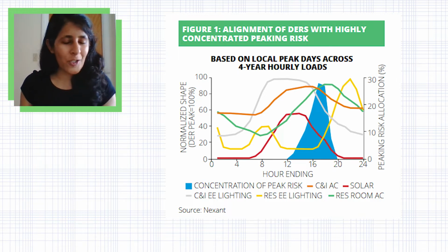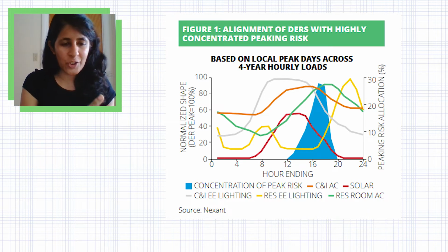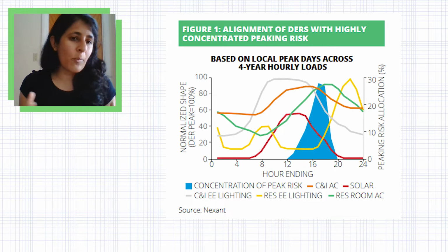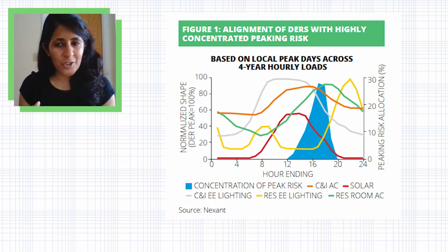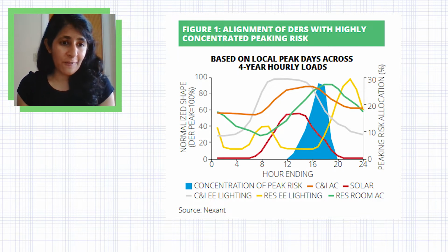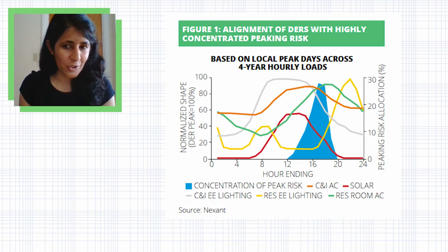Yeah, so the traditional way of addressing this peak load has been to build more power plants or to build more transmission and distribution lines, basically to build maybe a combustion turbine, which is typically the kind of unit you would have to address peak loads, and then building more of those wires that are transmitting that electricity to your house. And that's basically been the traditional way of doing that. But now with distributed energy resources and the value they provide to the grid, that serves as an alternative to this. And you can avoid a lot of that infrastructure on the grid, through distributed energy resources.